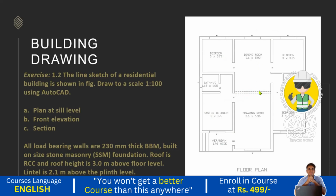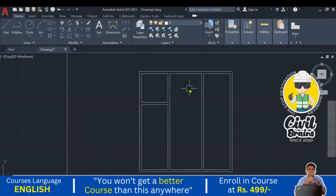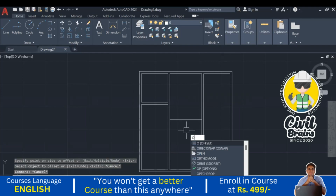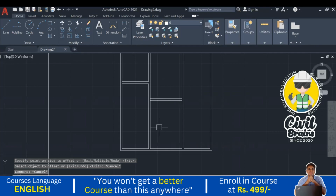Okay, what is that depth? That is 5.03. Okay, thickness is 0.23 only. So just go to the offset. I just take 5.03, press enter. Okay, again I will take offset 0.23, which is the wall thickness. Okay, this is the dotted wall. We'll do it later. Okay, I will tell you how to do that one. We'll do that one later.